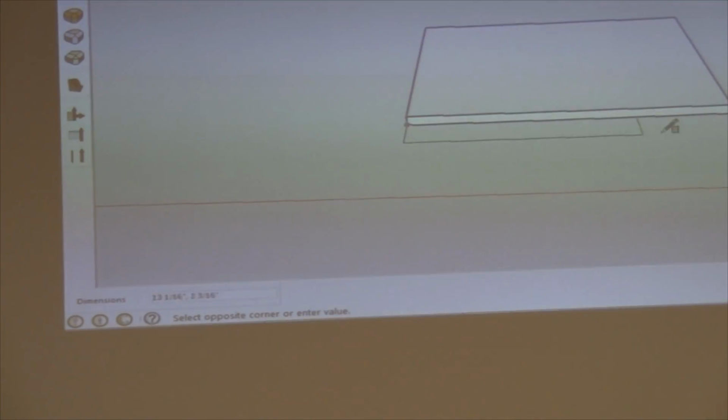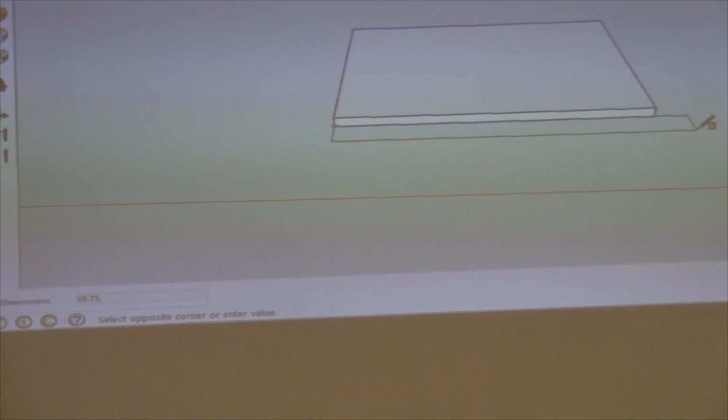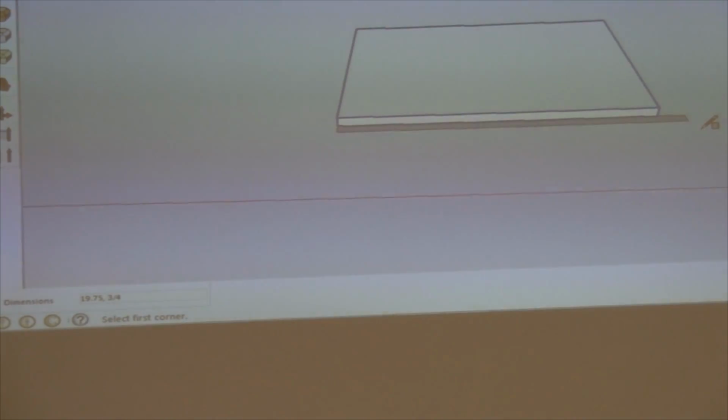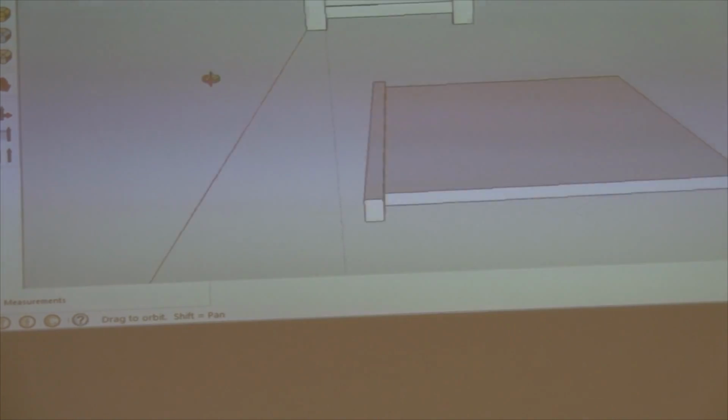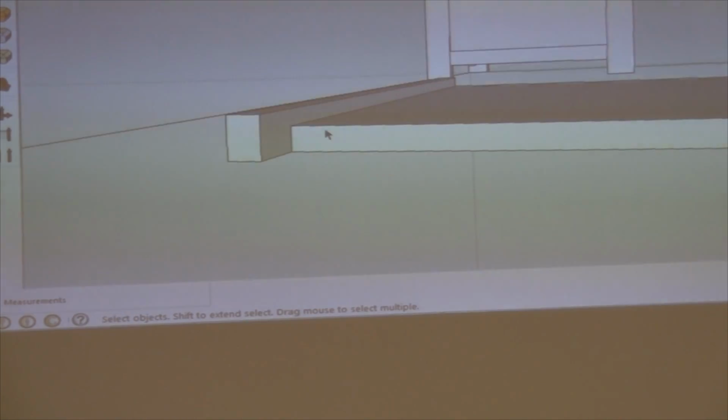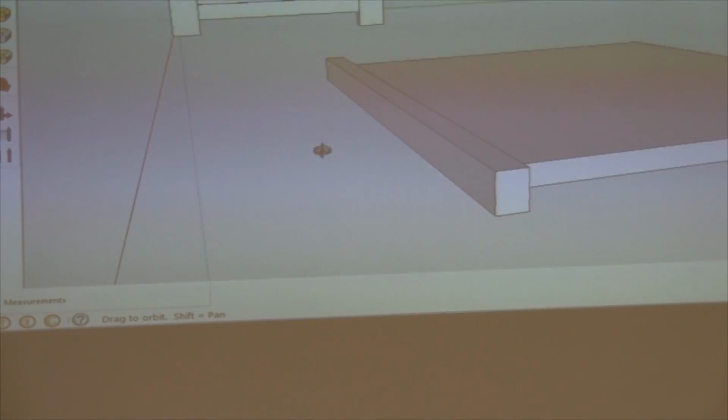The blocks are going to be 19 3/4 inches wide, for the front anyway, by 3/4 of an inch thick, and they're going to be 1 1/4 inches tall. So you'll see actually this is not oriented yet, but the frame of course is thicker than the panel.